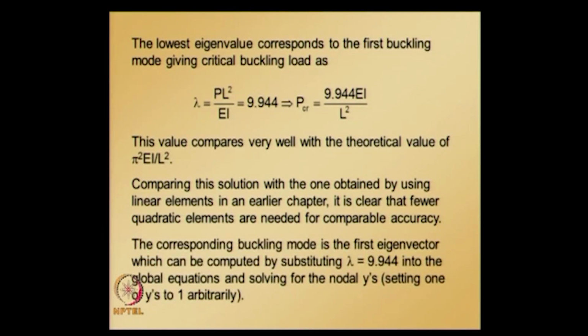The corresponding buckling mode, we obtained the buckling eigenvalue. The corresponding buckling mode in the first is the first eigenvector, which can be computed by substituting lambda is equal to 9.944 into the global equations and solving for nodal y values.